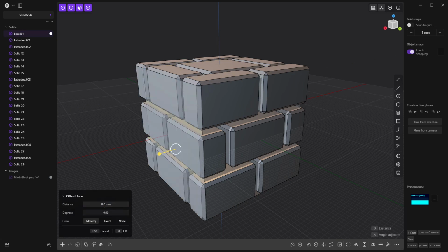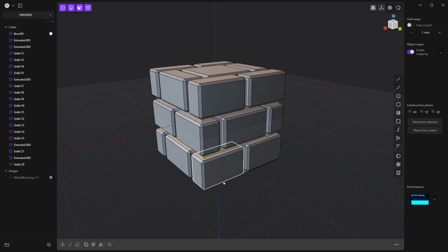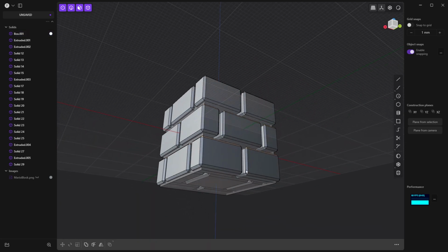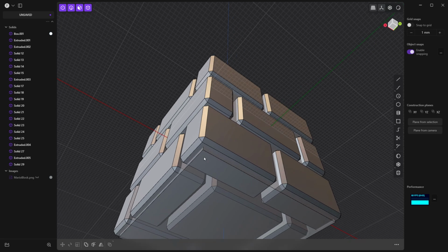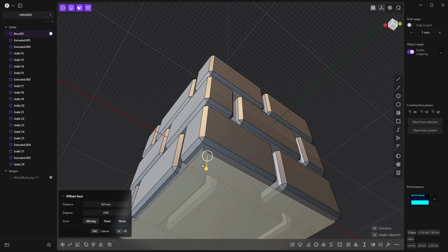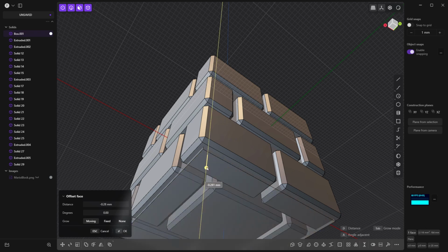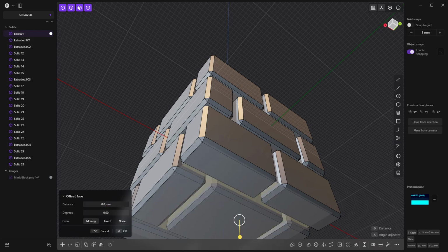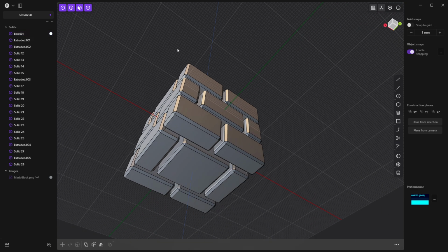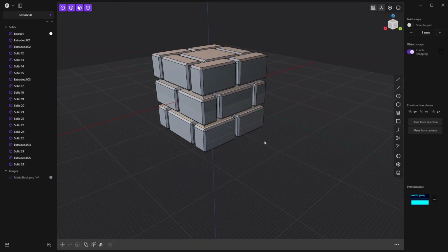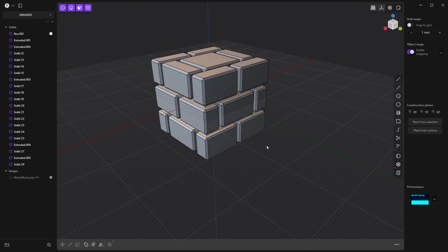And the last one on the bottom, when I've made bricks like this, I've actually designed a couple of objects that are like little storage containers with the top that threads off. A lot of times I leave the bottom flat because I'm 3D printing them. In this case, we're going to go ahead and offset it that -3 mm and make it sort of true to life. All right, the last thing that we want to do is combine everything together.